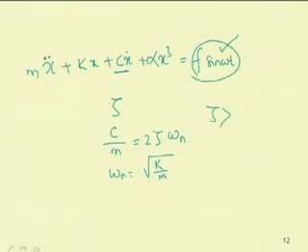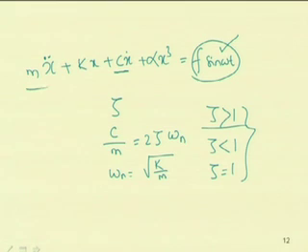If zeta is greater than 1, then the system is overdamped; zeta less than 1, it is underdamped; and zeta equal to 1, the system is critically damped. So, depending on the value of zeta, the system can be underdamped, overdamped or critically damped, and accordingly one can study the behavior of this Duffing oscillator. Most spring mass systems or most equipment subjected to a forced vibration can be considered in the form of this Duffing equation.